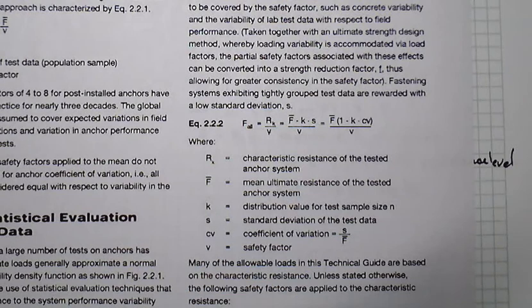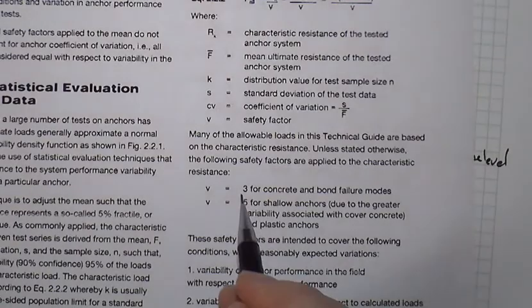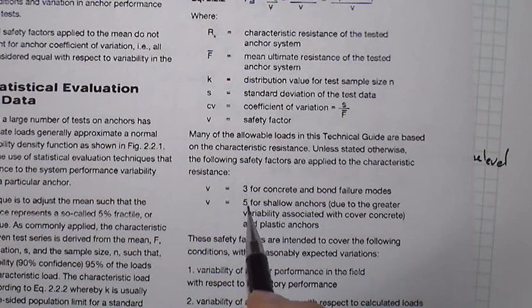Now, you will note that down here below they do talk about, for their specific local situation, safety factors of 3 and 5. And wow, wait a minute, that's a pretty big difference in factor of safety. The larger the factor of safety, in general, the more the limit state tends to be brittle, non-redundant, and more catastrophic in nature, or it might have a lot to do with the associated variability. Maybe there's larger variability, so to control the overall likelihood of bad stuff happening, they're going to go further away from the edge of the cliff.